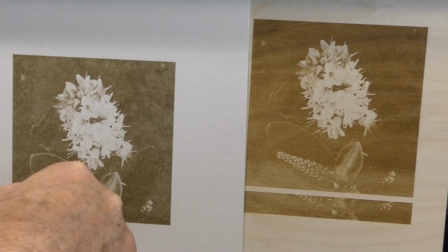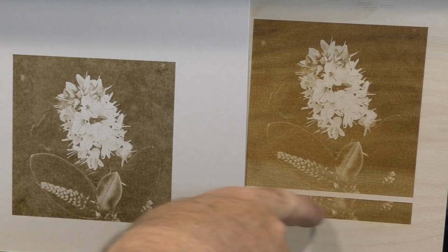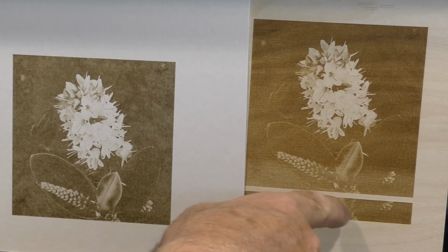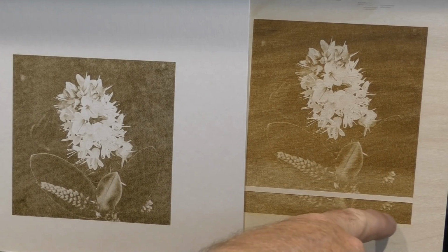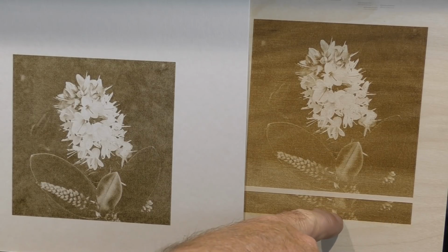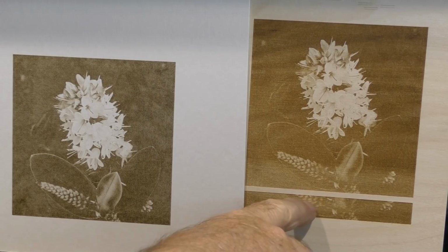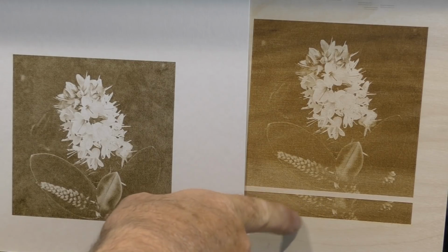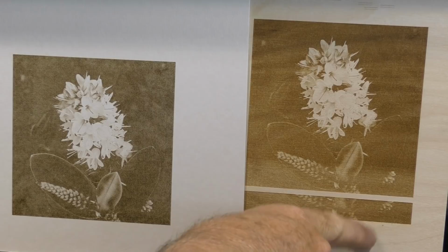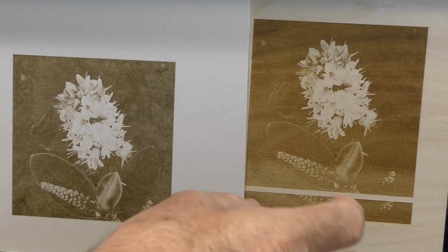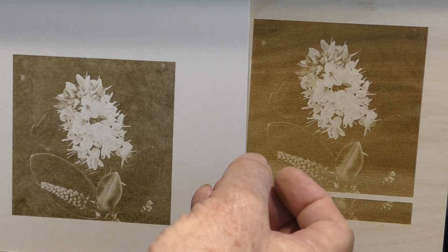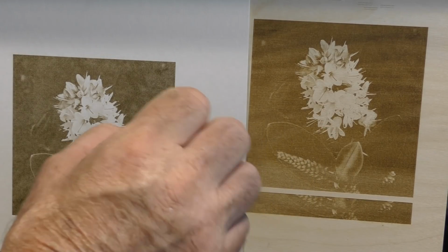Now, this bit here was where I started off with too much power. I started off with 20% power, and I had to back the power off to about 15%, I think, because I could see here that my browns were not the background colour, which is what I was expecting. So I was getting over burning here, and you can feel it in the texture, and in fact there's a small ridge across the bottom there. So my dots were definitely overlapping and over burning there. So by decreasing the power, I decreased the size of the dot effectively.